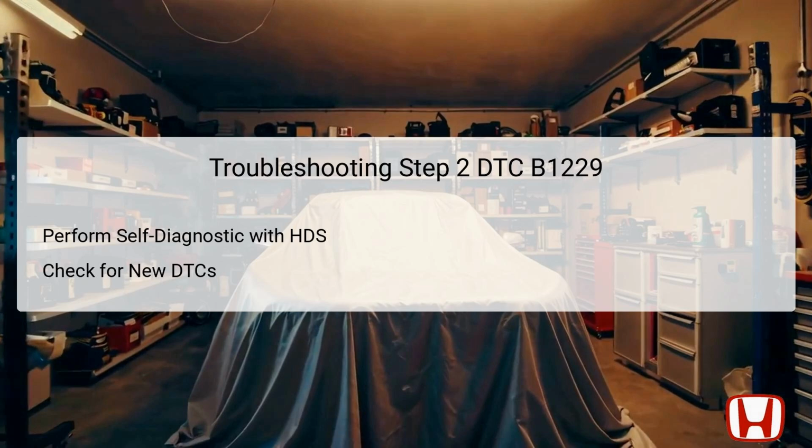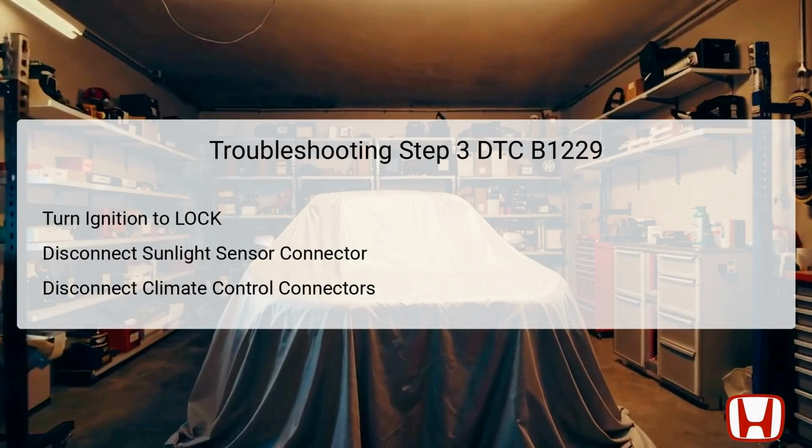However, if the code does not appear, the problem could likely be intermittent, and troubleshooting may require inspecting wiring and connections instead. In this step, you begin by turning the ignition switch back to the lock position, ensuring that all electronic systems are powered down. Once completed, disconnect the sunlight sensor's connector.